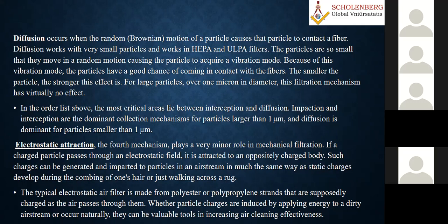If a charged particle passes through an electrostatic field, as you can understand from the name itself, you are trying to create charge in something. Electrostatic forces, you know, attract a particle to an oppositely charged body. Such charges can be generated and imparted to a particle in an airstream in much the same way as static charges developed during pumping of one's hair. Many of you, in school physics, must have learned about the Gaussian surface, Gauss's law, and theorem, maybe in 11th physics. The typical electrostatic filter is made from polyester, polypropylene, and similar materials.